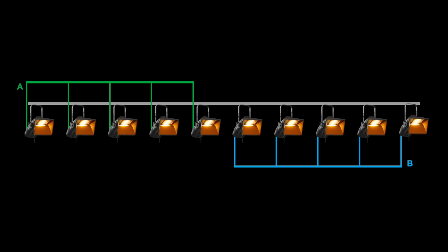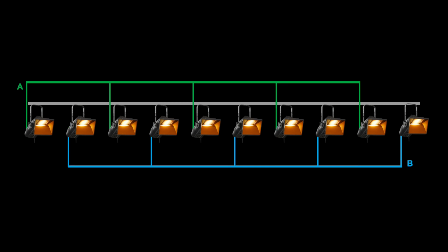Maybe you should plug things up in a way to better deal with that fault scenario. Maybe spreading those fixtures over 2 or more circuits would give you better resilience. For example, if you have a group of fixtures lighting a cyclorama or a backdrop, you might choose to wire them up on 2 circuits. But rather than grouping them as left and right, which would be easier when rigging the cabling on the truss, consider wiring every second fixture on circuit A and the rest on circuit B.